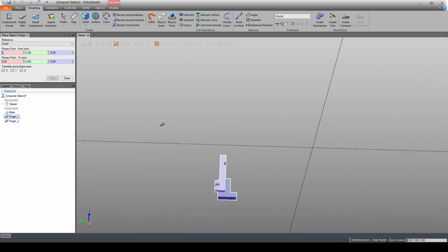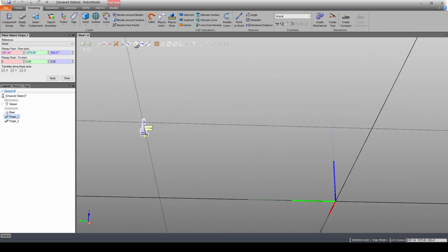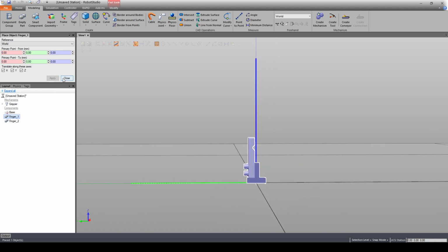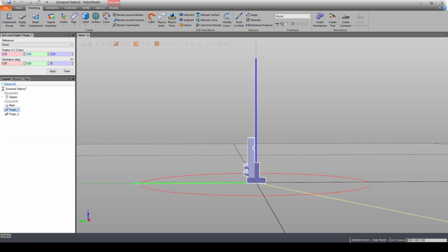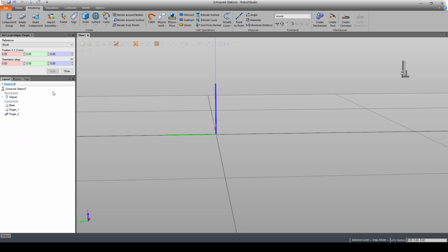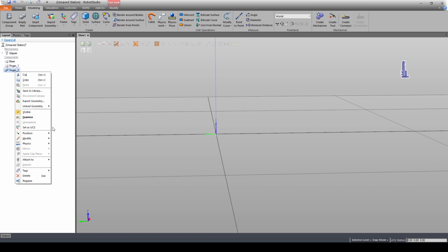So place, then we go and select this point, and then we select the frame, and we can place them at the 0 over here. Apply, and then we right click, modify, set local origin, and we make this position as their new 0. And we can do the same thing on this finger 2 over here.